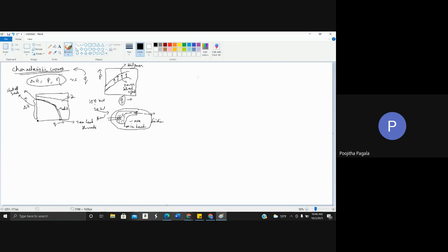And then let us look at the efficiency curve. Efficiency against flow rate. So for an ideal situation, you will have a 100% efficiency line, whereas in an actual pump, the efficiency initially increases and then it slightly decreases. Initially, it increases steeply, the efficiency, and then there is a slight decrease. So these three are the characteristic curves of a pump.